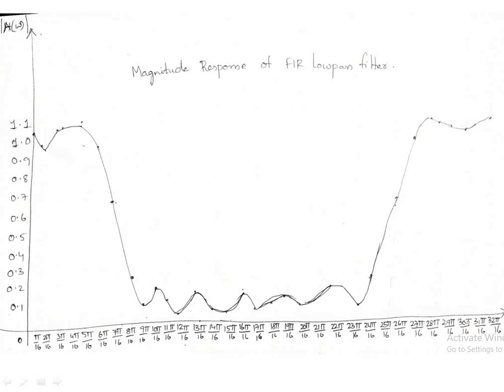Those optimal equiripple design criteria are generally used to design FIR filters to satisfy those specifications, as I said before. And this completes the lecture series on FIR filters, where we started with the simple key characteristics of FIR filters, and then we saw different design techniques such as the Fourier series method and the windowing techniques. We discussed 6 important and basic windowing techniques, starting from the rectangular window, triangular window, and the class of raised cosine windows such as Hanning, Hamming, Blackman windows, and also studied the Kaiser window. And then we have also seen some examples using those windowing techniques and the frequency sampling technique.